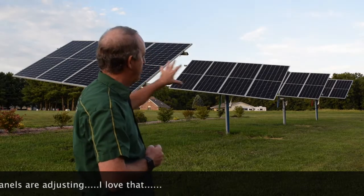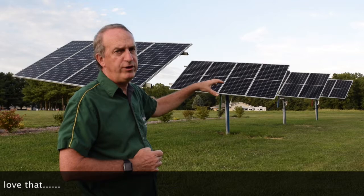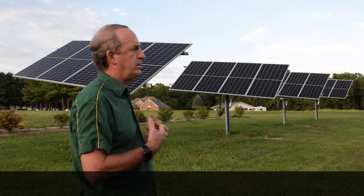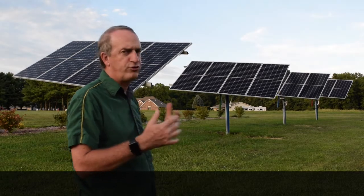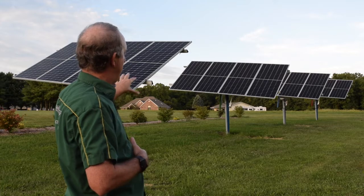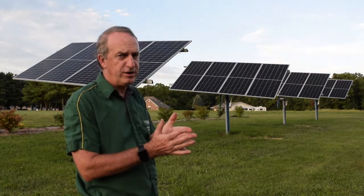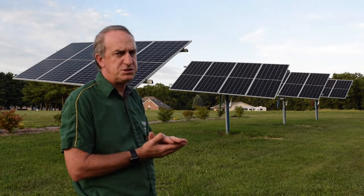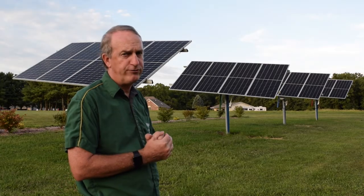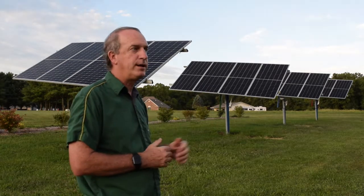If you start wiring them up, all of these on one string, then you would overload the inverter. The inverter can only take so much current, and it can only work with so much voltage. So as you're trying to figure out how to arrange your solar panels on strings to feed into the inverter, you're going to want to understand series parallel wiring, and you're going to want to follow the recommendations that come with your inverter. So that's an important consideration, which I learned pretty late in the game.